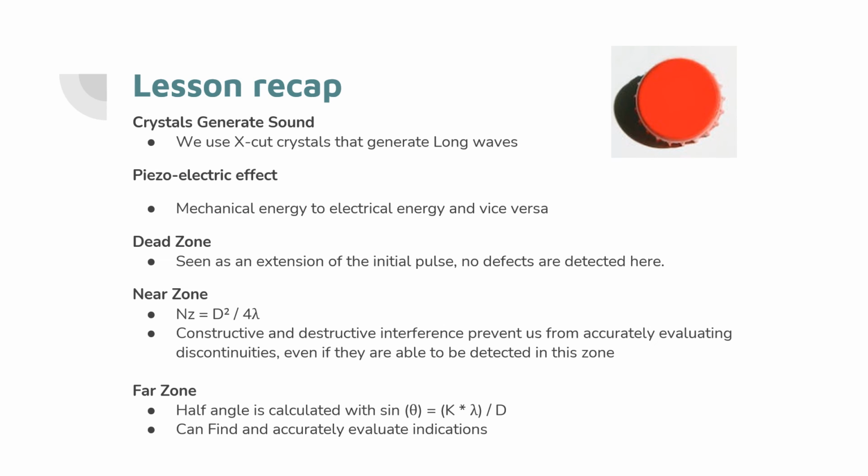Alrighty, so let's recap. We use crystals to generate sound. We use X-cut crystals that generate longitudinal waves. The piezoelectric effect is the ability of certain material to convert mechanical energy into electrical energy, and vice versa. The dead zone is that extension of the initial pulse, and no indications can be detected there.